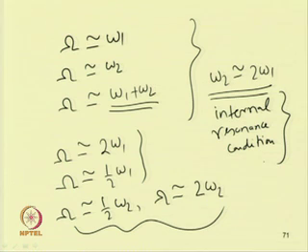In secondary resonance condition one can have the subharmonic, superharmonic. In addition to that we can have this combination type of resonance condition. And considering the internal resonance conditions also, one can get other different types of resonance condition in the system. One can study all those resonance conditions to find the response of the system.